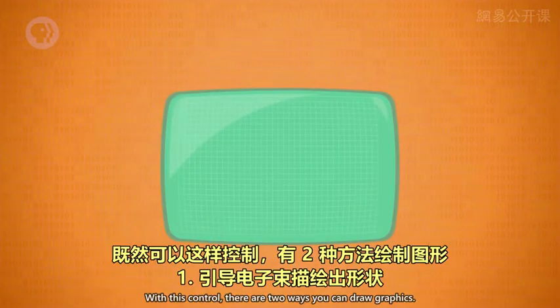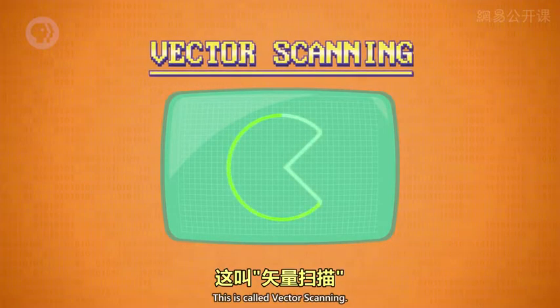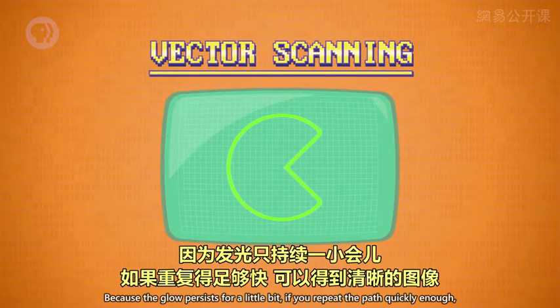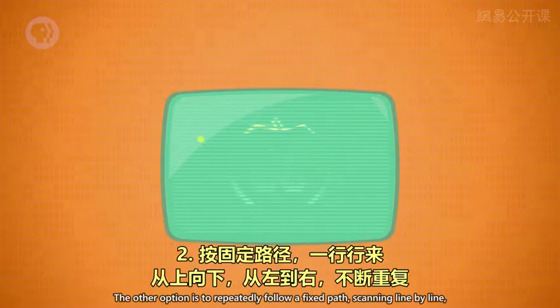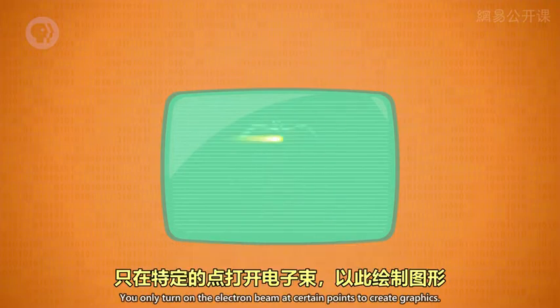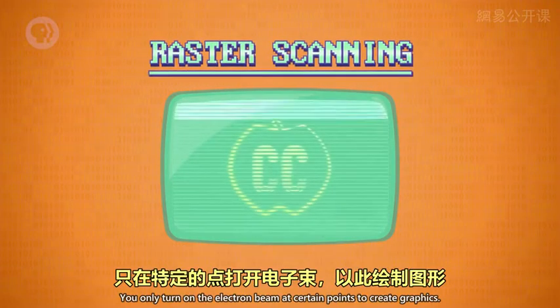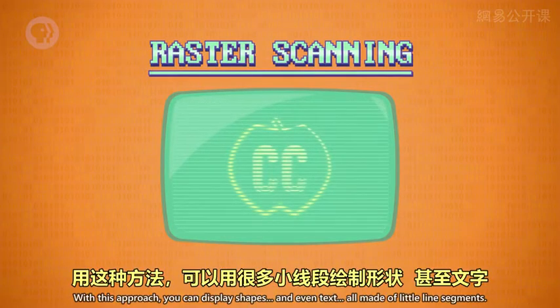With this control, there are two ways you can draw graphics. The first option is to direct the electron beam to trace out shapes. This is called vector scanning. Because the glow persists for a little bit, if you repeat the path quickly enough, you create a solid image. The other option is to repeatedly follow a fixed path, scanning line by line from top left to bottom right, and looping over and over again. You only turn on the electron beam at certain points to create graphics. This is called raster scanning. With this approach, you can display shapes and even text, all made of little line segments.